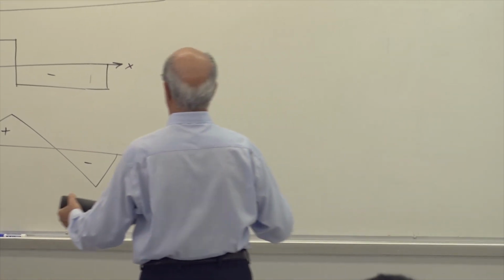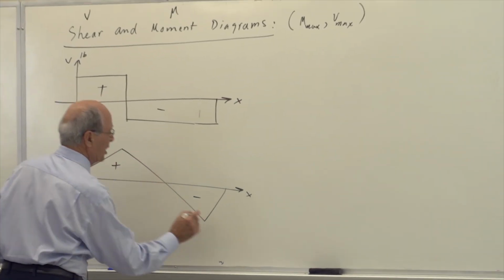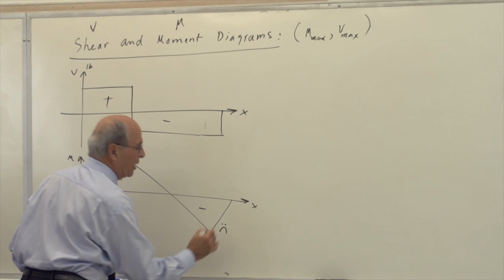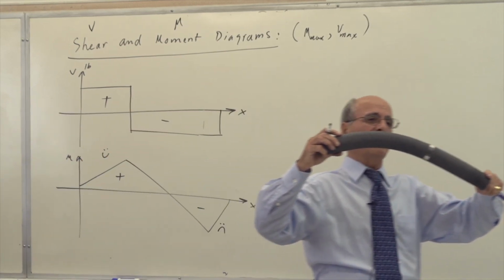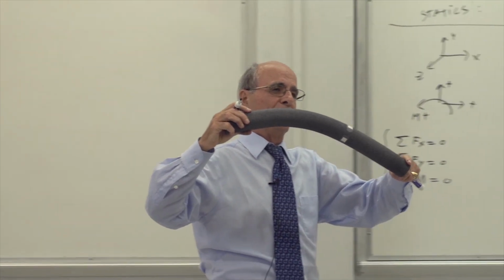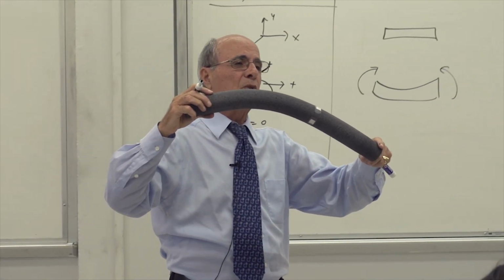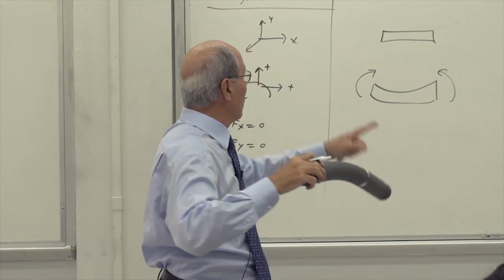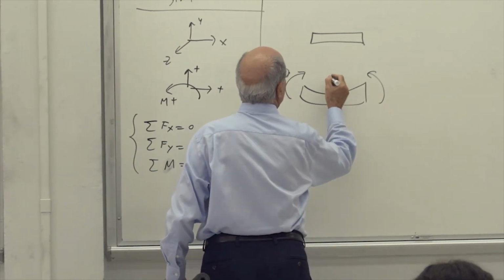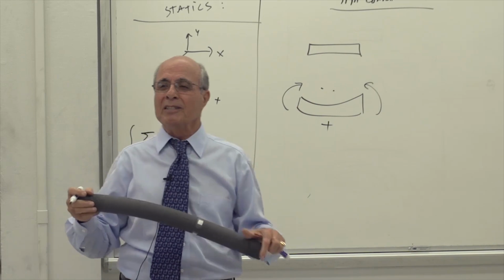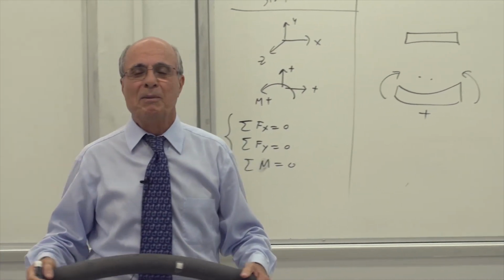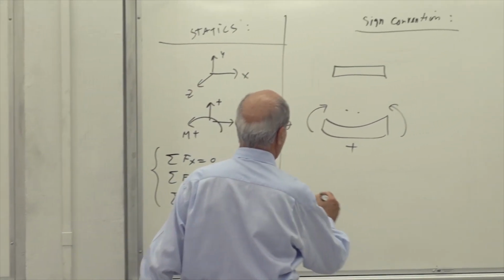So therefore, here, if this moment is this way, it is frowning. Yes or no? Look at this: is this beam frowning at us or smiling at us? Frowning. So the moment here should be plus or minus? Let's say a smiley face, we are going to call it plus. Of course, the frowny face, we are going to call it minus, which requires this action.